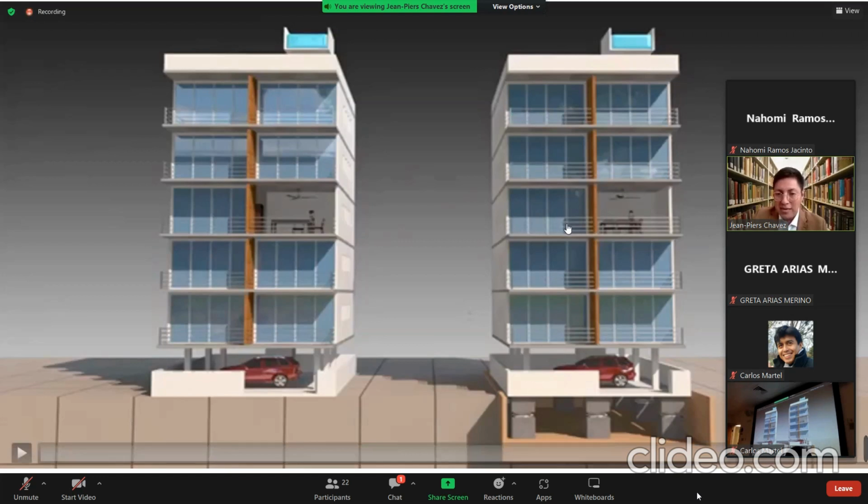But in contrast, the building on the right has the seismic protection system with this special device, LRB. This is the name of the special device. With this interface, you don't have any damage in the structure or inside the building, because the displacement is less and the acceleration is much less in contrast to the other building.